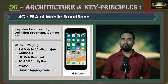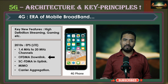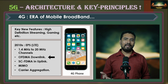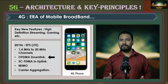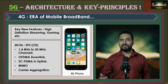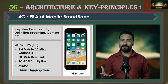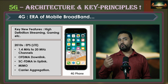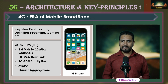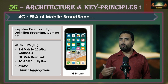4G supports bandwidth from 1.4 MHz to 20 MHz. 4G uses OFDMA technology in the downlink and single carrier FDMA in the uplink. OFDMA is a multiple access technology where a wideband carrier is split into many narrowband subcarriers, and they act as individual channels. Because of that, we can have wideband data rates that offer high throughput. At the same time, we can also use the benefit of better propagation characteristics from narrowband channels. 4G offers good broadband data rates, and because of that, it is generally referred to as the generation of mobile broadband.